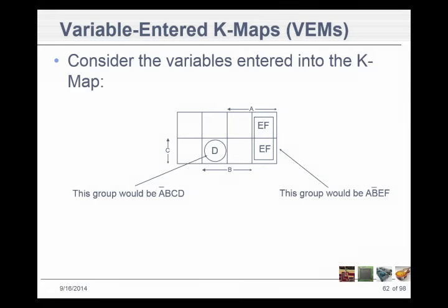On this other one, it's a lonely D out there. If it were a 1, we would be saying it is A naught, B, and C. But then there's a D in there instead of a 1, so we have to AND that D to that group.